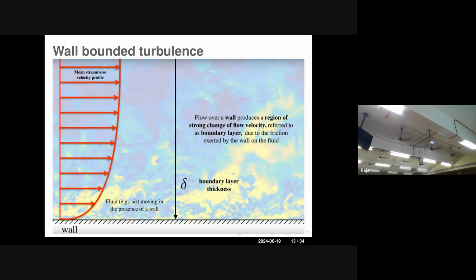If it is already turbulent flow, possibly there will be some viscous layers, some logarithmic layers, some mean flow. And flow comes, and what we are looking at is the energetics, the kinetic energy in the flow. There will always be small eddies and structures, and large scales, maybe with some kind of self-similar nature up to certain scales.